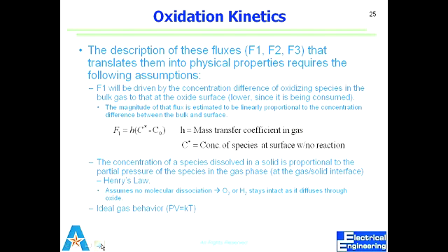The point here is that we seldom do this because we don't raise our temperatures and we don't make our gases travel from gas to solid. We seldom see that ever. Do we? Generally not. But in silicon, that's what makes these things happen. In diffusion, which is the introduction of dopants, and it's also diffusion here, because we have to get the oxide species to get to silicon to react. So, the partial pressure of the species in the gas phase.